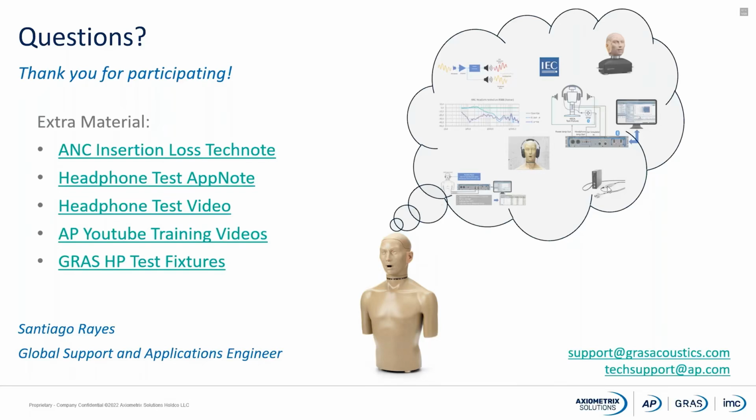Remember that the ETSI recommends using 8 different loudspeakers surrounding the head and torso simulator. That means that the sound field can be fine-tuned by changing the amount of signal that is played back through the different loudspeakers. So I recommend you to check on the ETSI standard, and the short answer is no. You don't need to have an anechoic chamber if your room is well isolated.